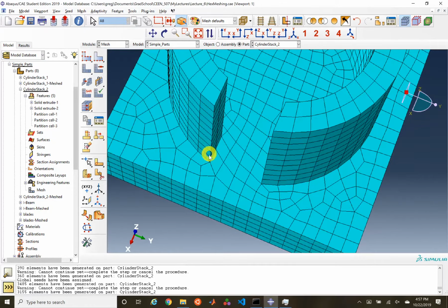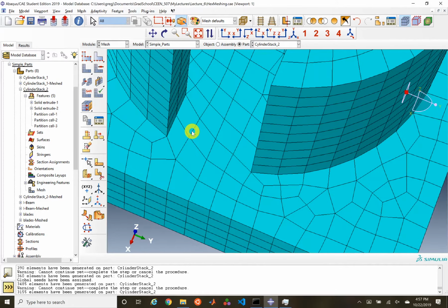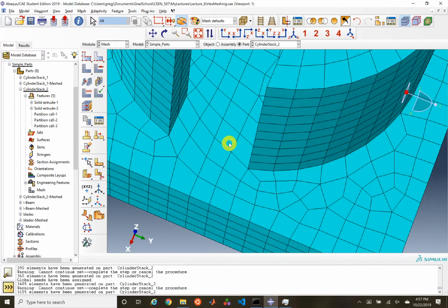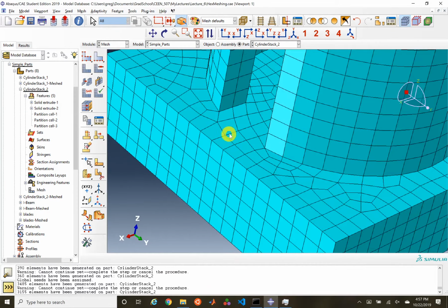Here are these two surfaces that have nodes that kind of line up, but you see how this element here tracks from this element on the outer surface to the inner node on this surface there. So essentially, Abaqus doesn't know that it can communicate this information across, and so this is the art of deciding how to communicate information across cells to get yourself a beautiful mesh.